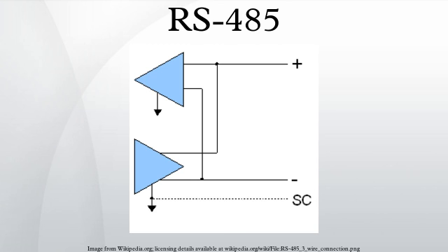In contrast to RS-422, which has a single driver circuit which cannot be switched off, RS-485 drivers need to be put in transmit mode explicitly by asserting a signal to the driver. This allows RS-485 to implement linear bus topologies using only two wires. The equipment located along a set of RS-485 wires are interchangeably called nodes, stations or devices.